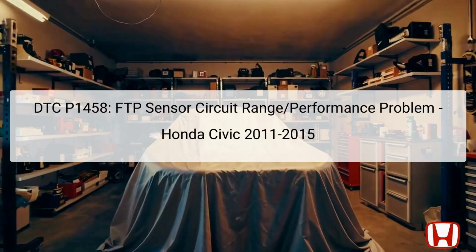DTC P1458 indicates a problem in the fuel tank pressure sensor circuit within the Honda Civic models from 2011 to 2015. The FTP sensor plays a critical role in monitoring the fuel tank pressure within the EVAP, Evaporative Emission Control System, which prevents fuel vapors from escaping into the atmosphere. This component is typically located near the fuel tank, connected to the EVAP canister, and works by sending pressure readings to the Engine Control Module, ECM. A malfunction in this sensor can lead to increased emissions and may trigger the check engine light.